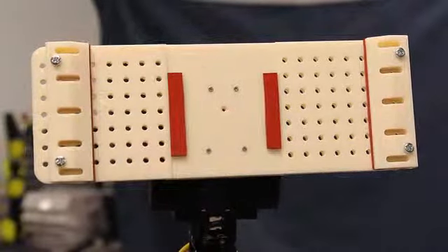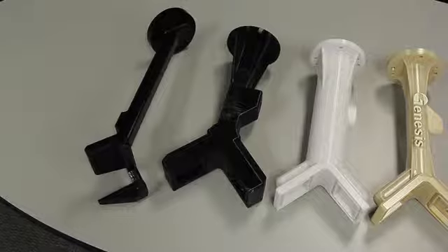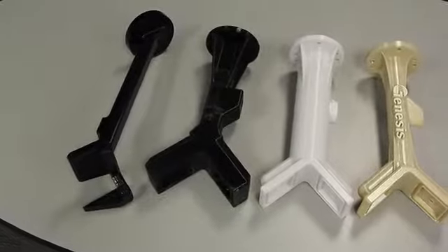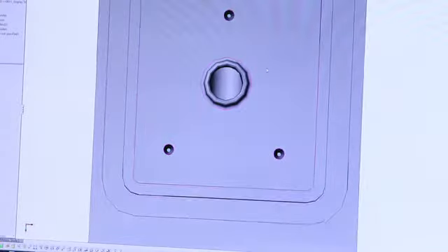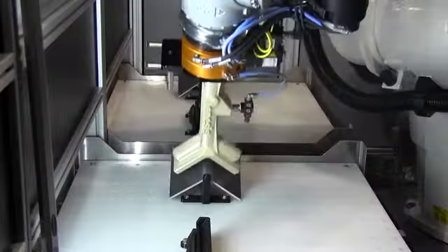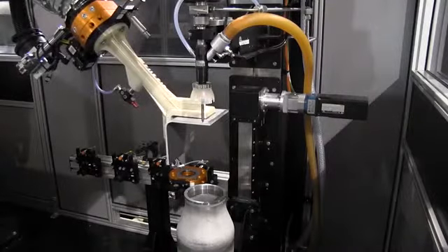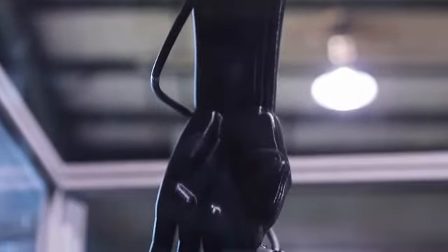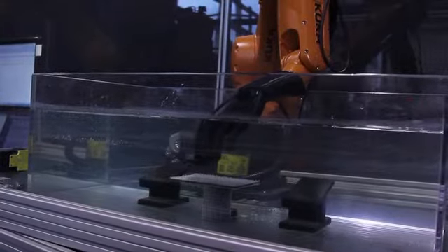than ever before. The process starts by designing an end-of-arm tool in a CAD program. When using FDM technology, designers have greater freedom to create an end-of-arm tool that is not limited by traditional machining methods. For example, FDM can incorporate internal passages to serve as vacuum channels. These enable the robotic tooling to vacuum grip parts without external vacuum hoses that can be damaged or snagged. What's more, FDM end-of-arm tools can be 3D printed to include complex or organic geometry while keeping manufacturing costs low.